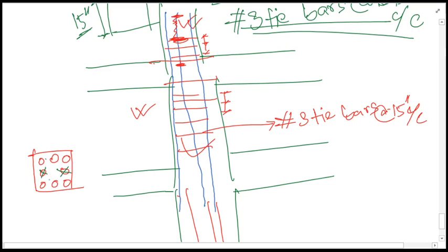Say you have cut these 2 at a time, then after a sufficient distance, or going to another story, you will be cutting these 2, and finally this 4 will be continuing further. So not at a time you can cut all the 4 at a time. Keeping symmetry, you just cut off 2. In another story, after going sufficient distance from the joint, you cut off these 2. That's how you can proceed.